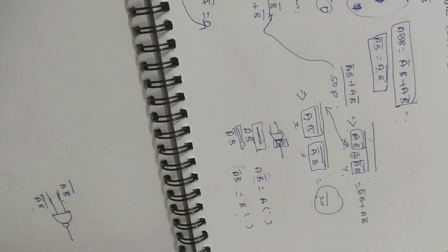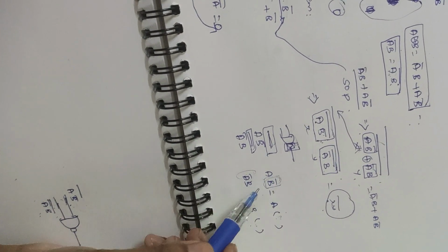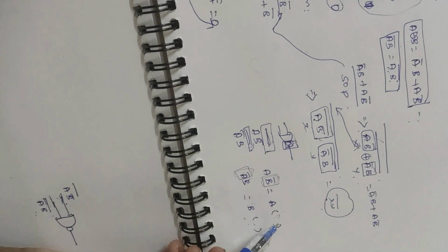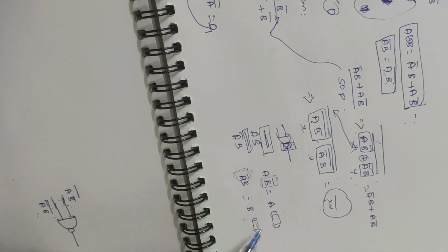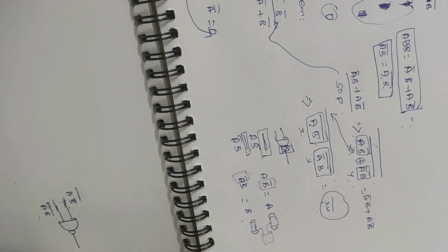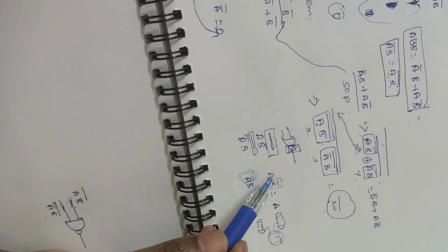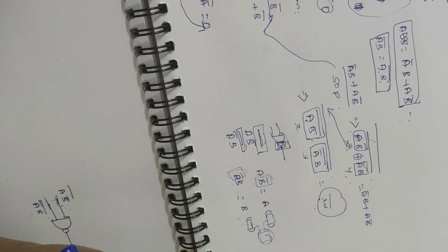So we are trying to implement using 4 gates, so we won't be doing it straightforward as that. Instead what we are going to do, we will be putting one value here, and here that will be common, only 1. So for this one NAND gate only we need, and to do this operation we need another 2. So with only 4 NAND gates we are trying to implement.